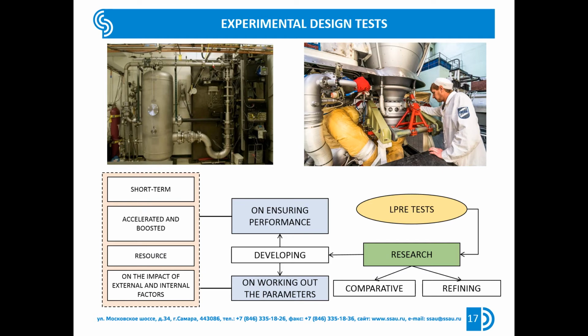necessary. In this case, the operating conditions are tightened, making it possible to shorten the test time. Such systems typically operate in cyclic mode. With accelerated tests, the pause time can be eliminated and the operating time shortened. In operation, the level of basic parameters is set higher than in normal operation, while the number of cycles remains unchanged.